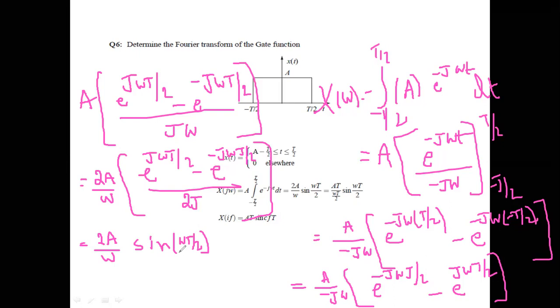Actually, the ω is nothing but 2π f. The sinc function is sinc θ. Now we got sinc θ is equal to sin(πθ) by πθ. Okay, my dear students. So in the denominator already ω is there. We need T/2 multiplied in the denominator and take it to the numerator also, T/2.